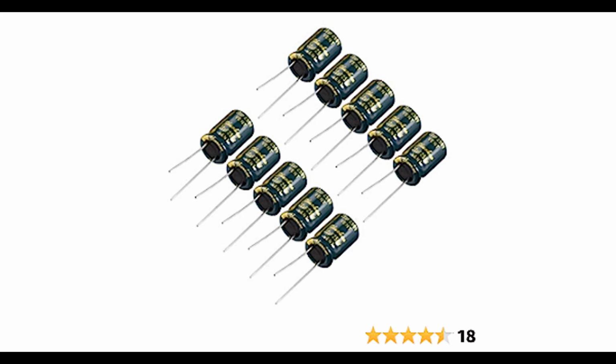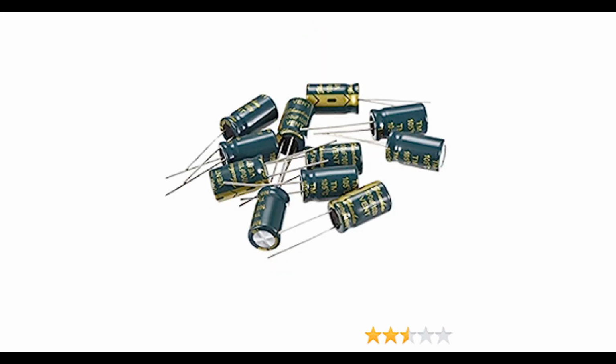Electrolytic capacitors. The most common type of polarized capacitor is the electrolytic capacitor. Electrolytic capacitors use an electrolyte soaked in a porous material as the dielectric. The anode is typically made of aluminum in aluminum electrolytic capacitors, or tantalum in tantalum electrolytic capacitors. Voltage polarity. It is crucial to connect polarized capacitors in the correct polarity. Reversing the polarity can lead to the breakdown of the dielectric layer, electrolyte leakage, capacitor failure, or even damage to other components in the circuit.